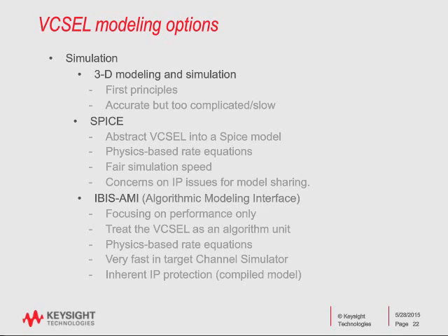It allows us the ability to do lots of bits and or lots of different simulations, swept simulations, so that we can examine the design space. We can try different things. And with the challenges we're facing, things like high-order modulation that we talked about earlier, the ability to do many simulations is a good thing. And of course, the nice thing, as I mentioned earlier, is that there is inherent IP protection in IBIS-AMI.